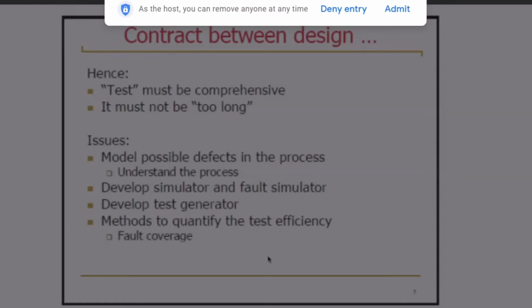If you consider a fault at a time, it will result in a different output compared to the absence of that fault. When the output changes by enabling or disabling the fault, you can say that the input vector, the vector which is the result of the test generation process, is detecting the fault.